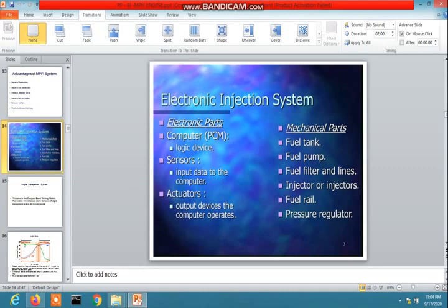Second, the atomization of fuel is independent of crank speed, and therefore starting will be easier. Better atomization and vaporization will make the engine knock less. Variation of air-fuel ratio is almost negligible.